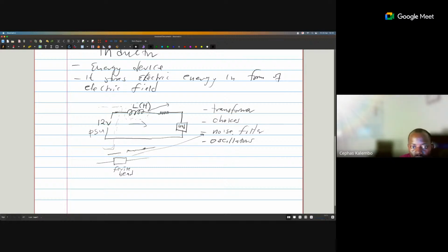So this might not be clean. In fact, even what I've drawn here is also not clean. A proper DC must be flat with no issues like that. Now, if this is what you are going to use, what's going to happen is that your phone will probably not be able to charge properly because of these transients. It will even start heating.